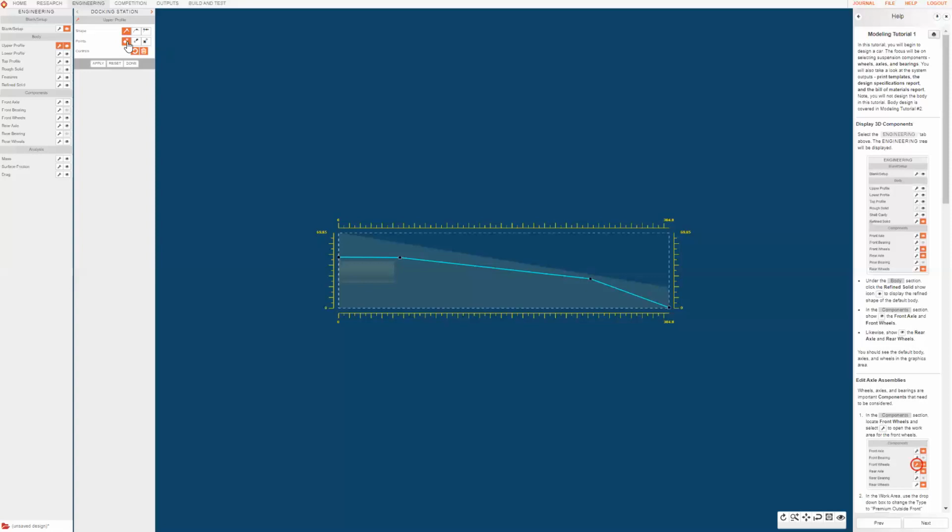So let me show you how to add a point. Let's say we want to add a point here on our line. Now we've added it. Now we want to move it. So you can take these lines, you can move these shapes here, and watch what happens if I switch to curve. See, we can curve that out. Let's say we want to bring this down a little bit.